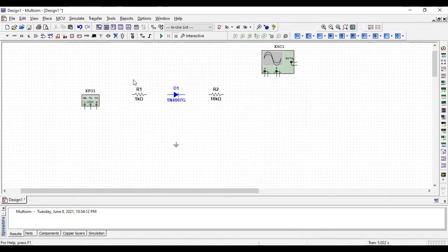All right, before going into the connections, let me tell you what these components are and why they are used in this whole circuit. This is the initial resistance, and it is used to control or maintain the current. We are all familiar with this diode. It's a PN junction diode, a one-way conductor, and it conducts only in forward bias. And this is the load resistance, which is used to measure the power consumption of the circuit. If you want to measure the power, you can easily calculate it using the relation P equals VI, and we all know how to calculate voltage and current through the circuit.